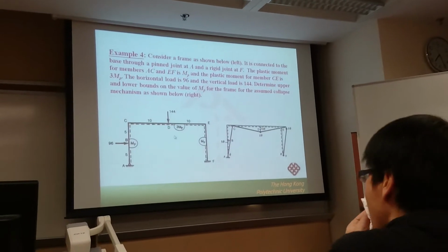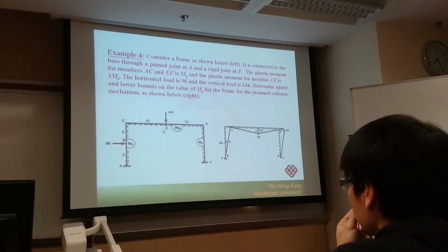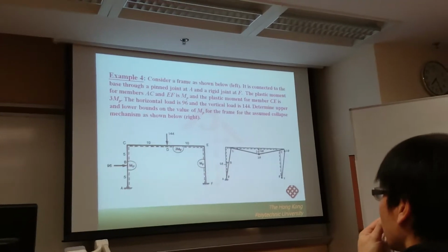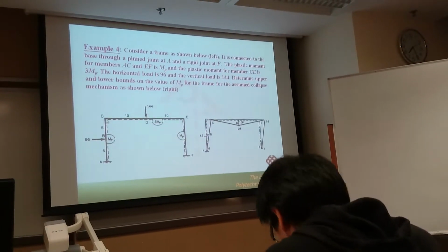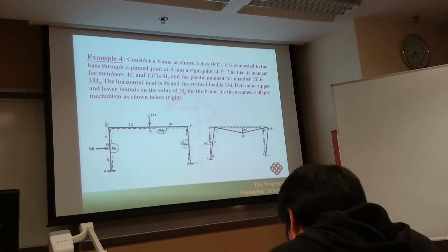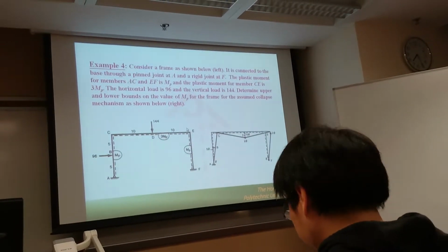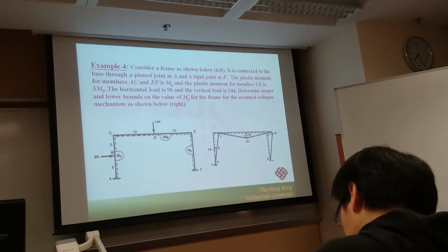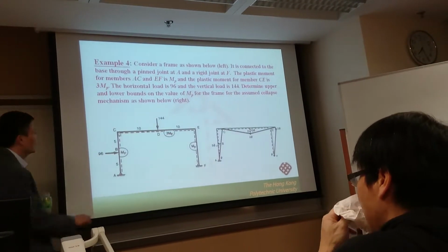And then we go back to the original system. If you go back to the original system, how about the virtual displacement? You have to introduce it to calculate the moment at point C. If you want to calculate the moment at point C, you can replace this point by a hinge and one unknown moment. Then because point D and point E are allowed to rotate, we can have a rotation at point D and a rotation at point E. So we can introduce a virtual displacement like this.